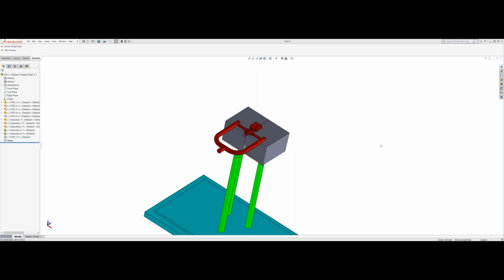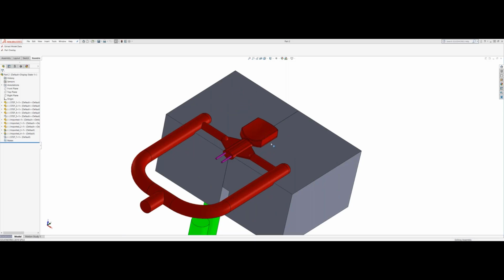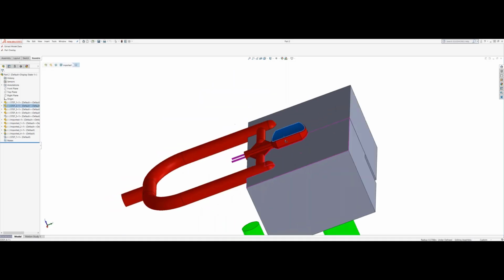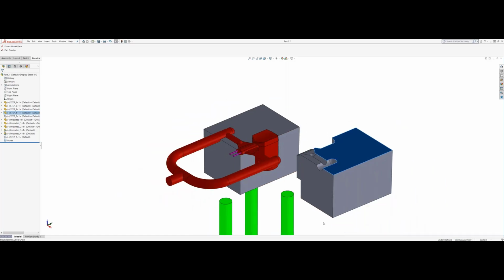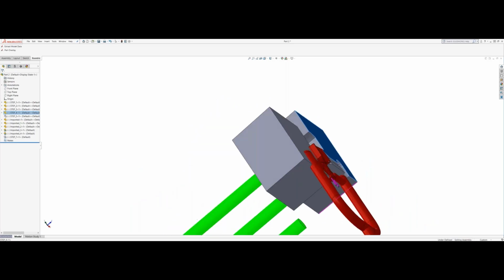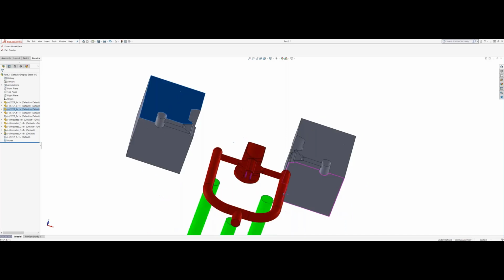We've got the runner system. The cavity forms this top section here, and little portions of it, but the meat and potatoes is, so this was a manual tool. Normally in a production setting, you would have these as slides, but this was a low volume prototype. And so we have these two hand picks that form the majority of the part.